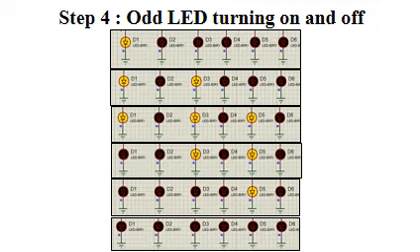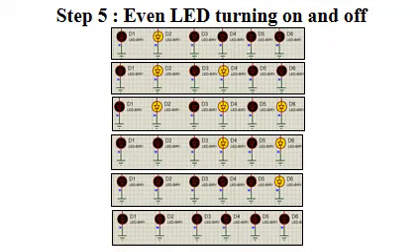The top image shows that the first 0 number pin connected LED is turned on, then the next odd LEDs will turn on sequentially with a delay of 300 milliseconds after it is turning on, and in the same sequence it will turn off. Here we can see the turning on and off sequence of even LEDs. First 1 number pin connected LED turns on, then 3 and then 5 number pin turns on. Then they turn off in the same sequence. This is our desired output.